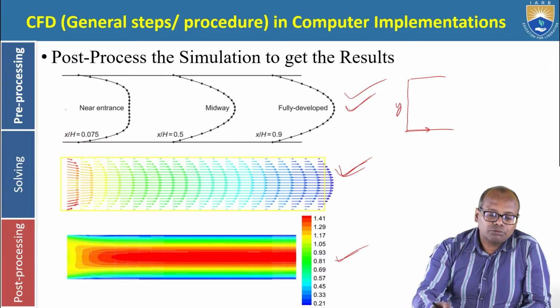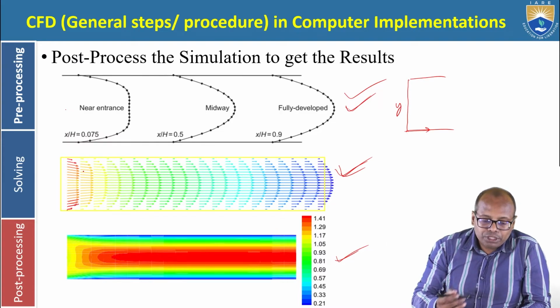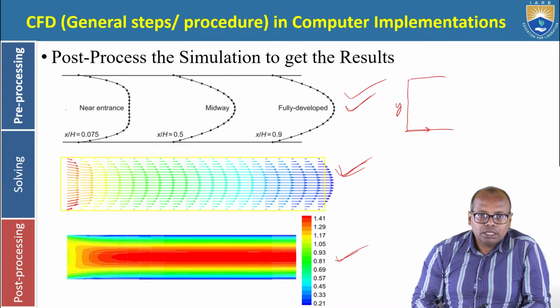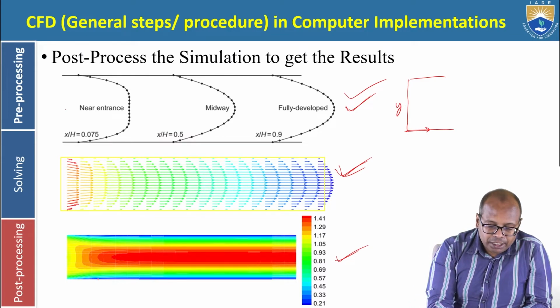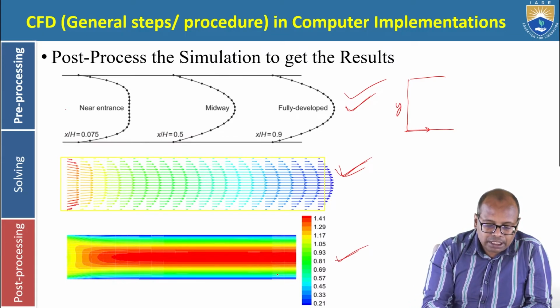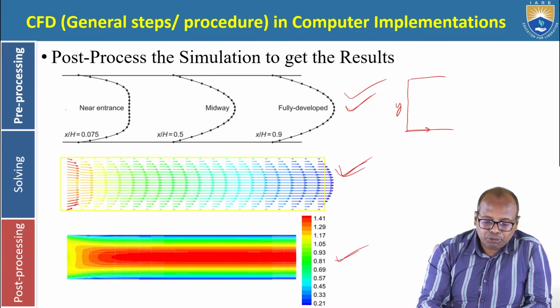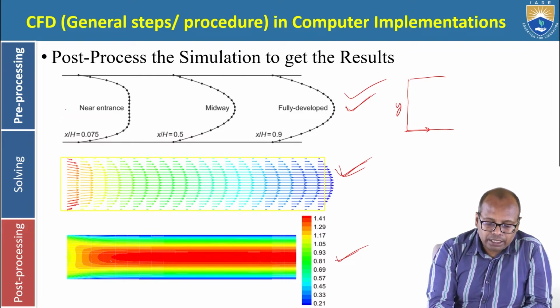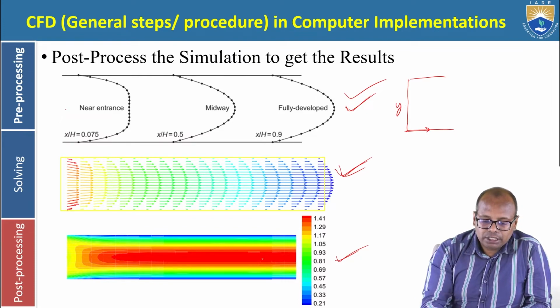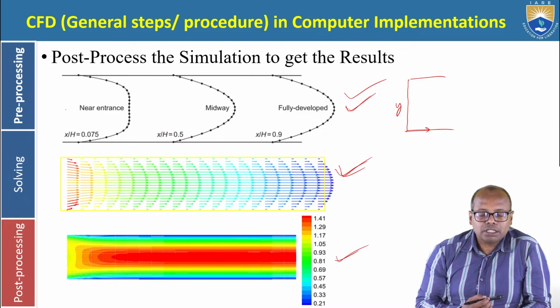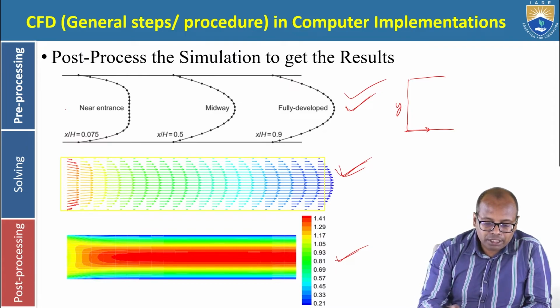Here we have given it as vectors. Now in the contour, I am identifying all the regions with the same velocity. This blue color line is showing approximately 0 velocity, and the red color zone, the intermediate core zone, is showing that the maximum velocity is in that region, and the yellow, green, all different shades.